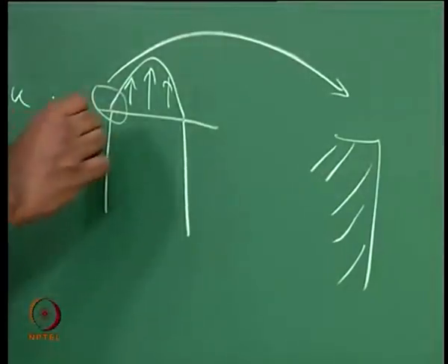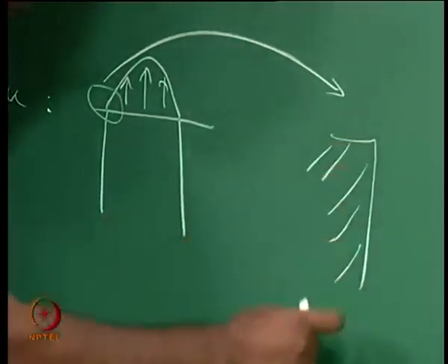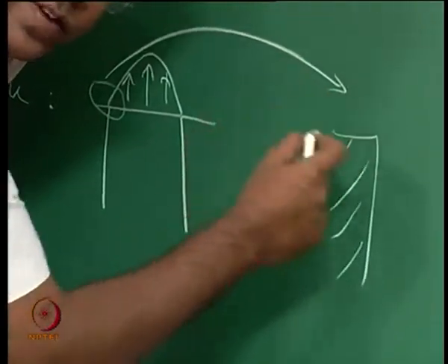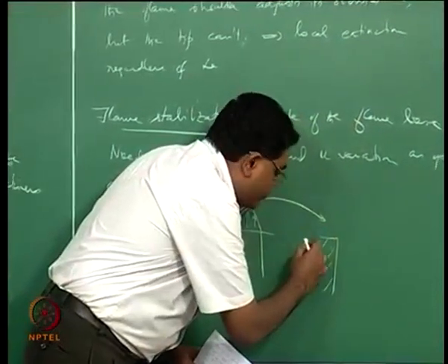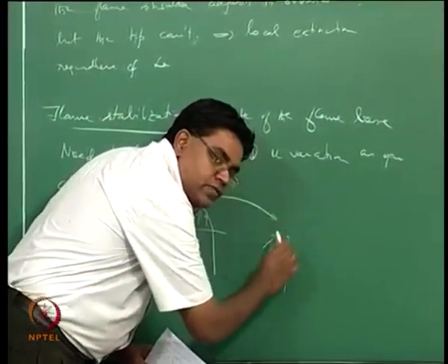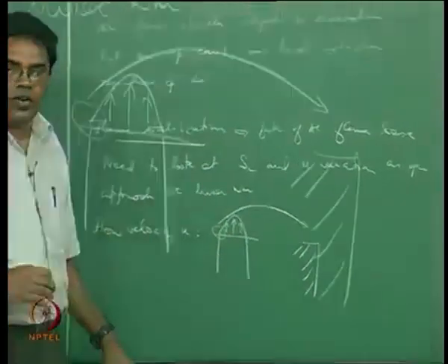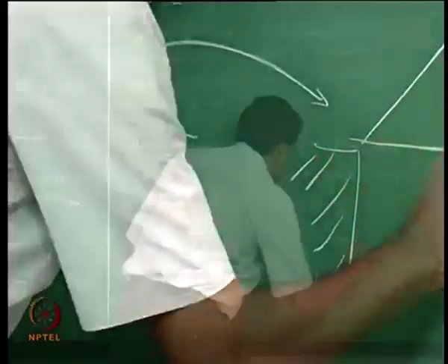Now what we drew as a line has suddenly become not a thick block. I'm even exaggerating and going further into saying that this is almost like a semi-infinite solid filling one quadrant, with the corner here corresponding to that burner rim, and the flow velocity is locally linear.